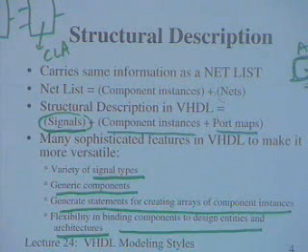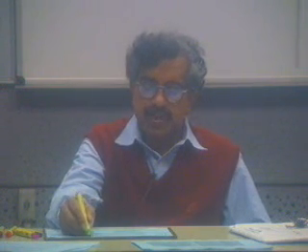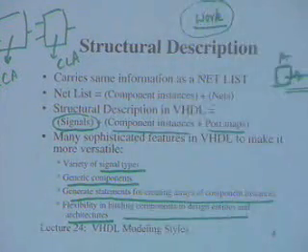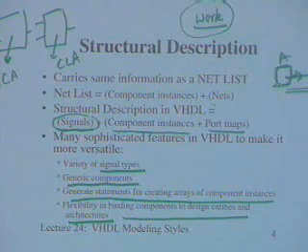That is, you have the template, you have the entity, but the architecture that this particular entity will use can also be different. And even there is a notion of libraries. Typically whenever you start working with VHDL, there is a library called work created. All the designs that you are doing go into this library called work, which is a default library for the user.